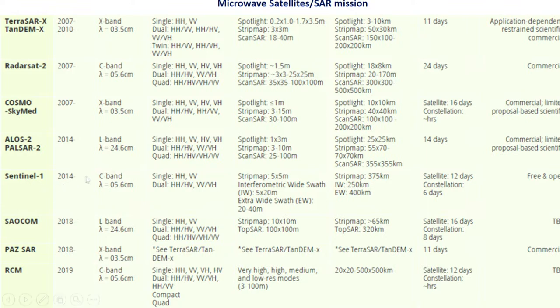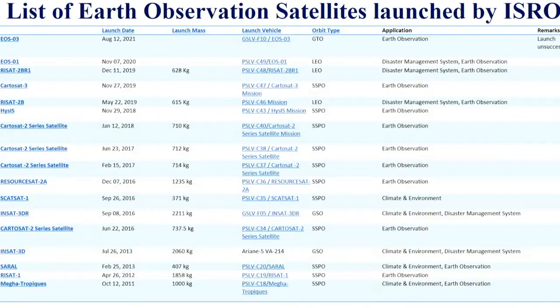Here you can see Sentinel is C-band, ALOS is L-band, Cosmo is X-band, Radarsat-2 is C-band, TerraSAR is X-band. L-band is very good actually, but due to the limitation of budget, we use Sentinel-1. And if we get some very serious anomaly, then we can go for ALOS PALSAR, so that we can go a little bit deeper and get the confidence level of the future earthquake.